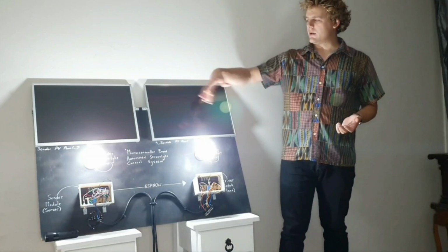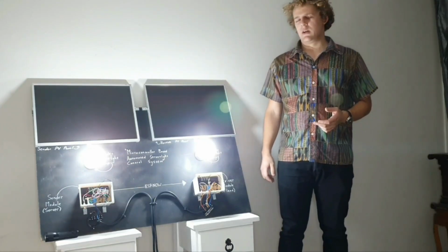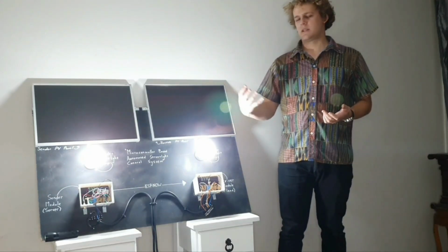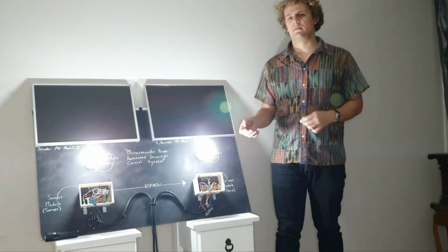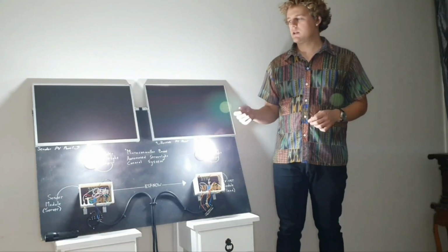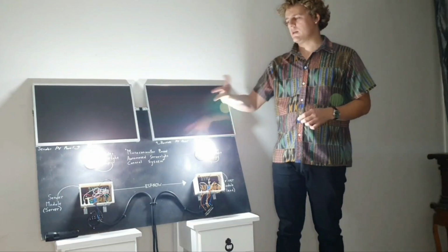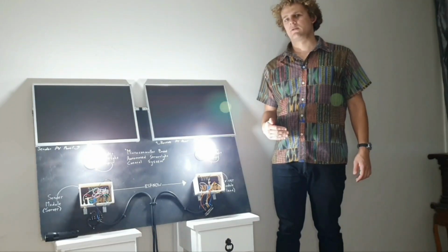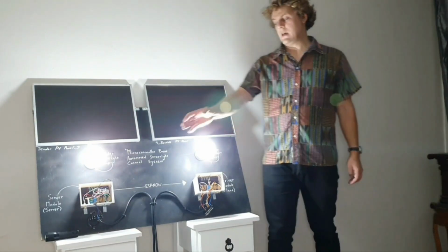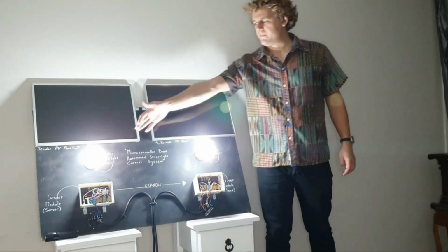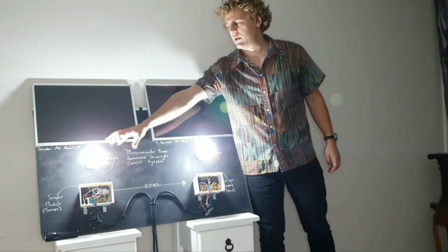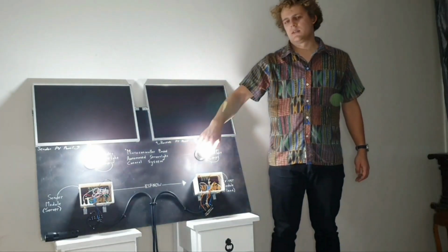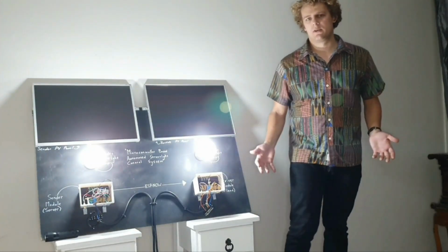So at the moment the street lights are on, and what we will do now is I will simply use a light source. I'm going to use a torch to deactivate the system through the LDR, through the day-night switch. So I will basically just introduce light to the LDR, and then we will see the system switch off, and two things will happen. If there's light applied to the LDR, then this module over here will switch its relay off, and this light will go off, and at the very same time it will send the ESP-NOW signal and tell this one to also switch off. So let's have a look at that.